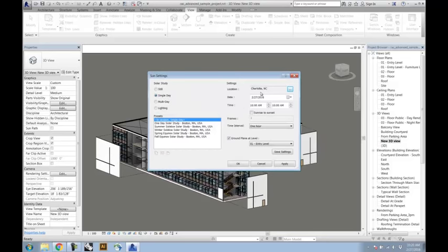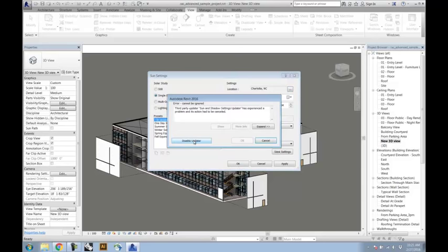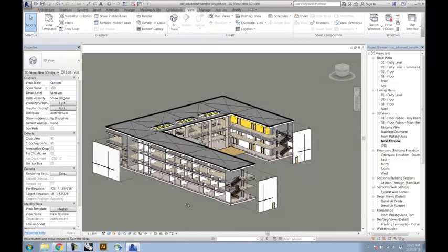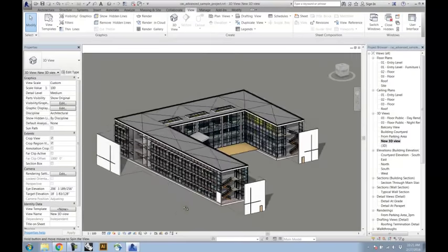Anyway, what I'm concerned with is getting the location set, and potentially getting the day and time set within the sun system. Because the site was already set as Manchester, New Hampshire for this project, it gives me an error as I try to adjust the sun's locations.